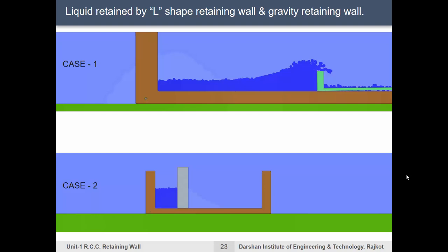While for a granular material, K is always less than unity, which means that vertical pressure will always be greater than horizontal pressure. Hence, granular material is able to generate a large vertical pressure on the projected leg of a retaining wall compared to the horizontal pressure on the vertical stem. L-shaped retaining walls are more justified for retaining granular material than liquid.